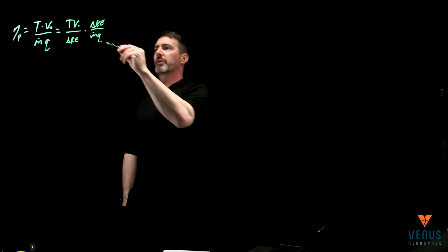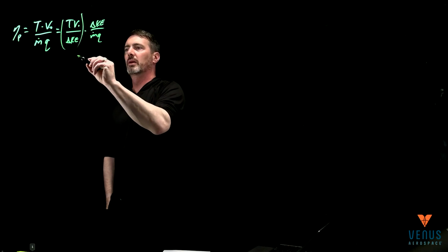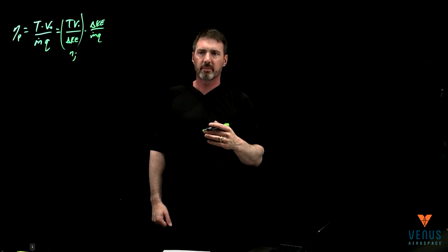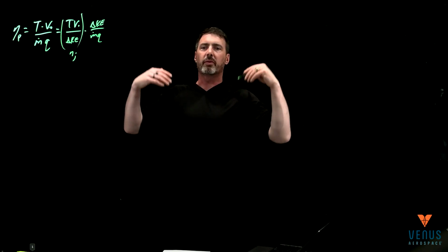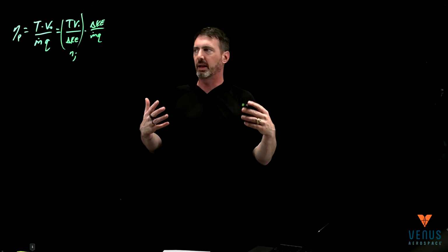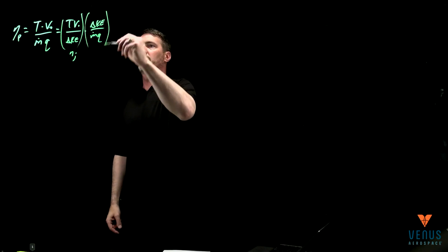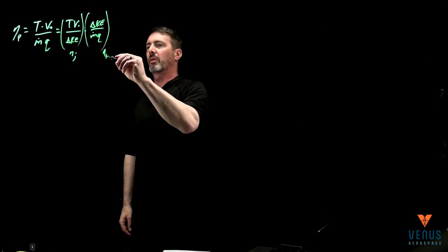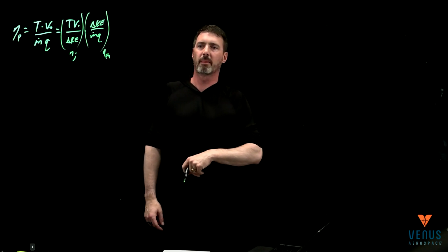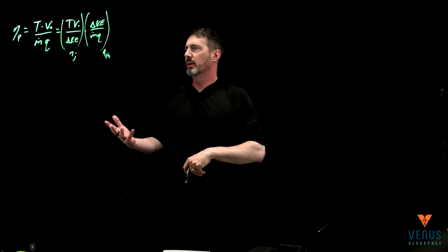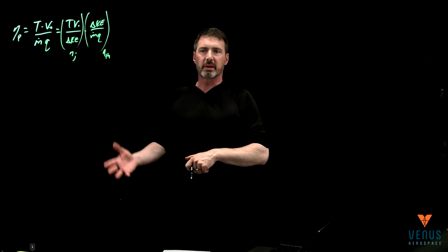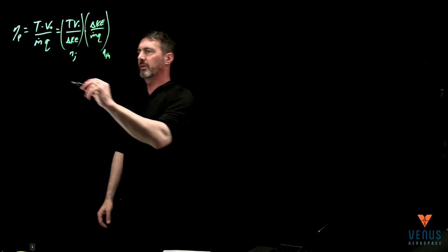This first term we identify as our jet efficiency: the thrust power compared to the change in kinetic energy. The second term, the change in kinetic energy compared to the heat added, is our thermal efficiency. Let's look at the jet term first.